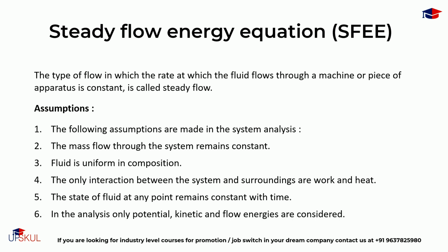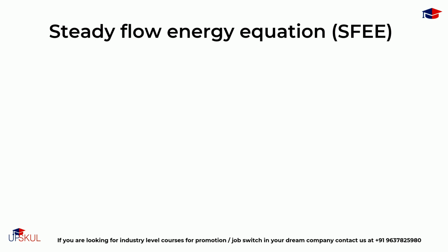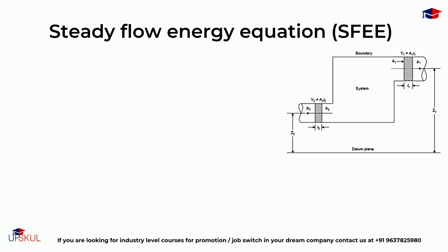This is a schematic flow process for an open system. A wide interchange of energy may take place within an open system. Let the system be an automobile engine with inlet manifold at the first state point and exhaust pipe at the second point. There would be an interchange of chemical energy in the fuel, kinetic energy of moving particles, internal energy of gas and heat transferred, and shaft work within the system.